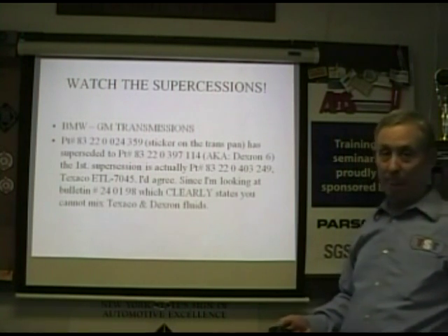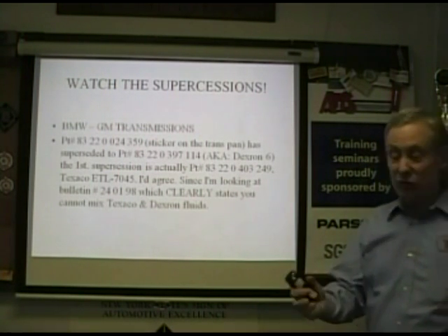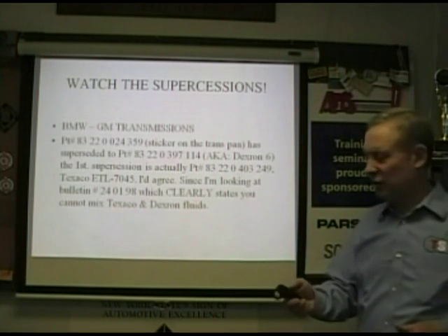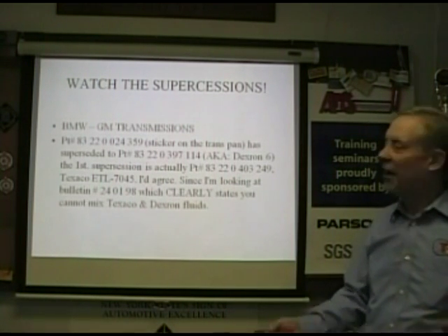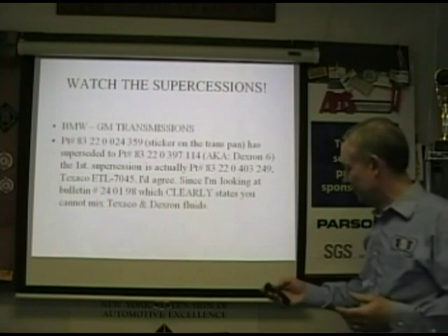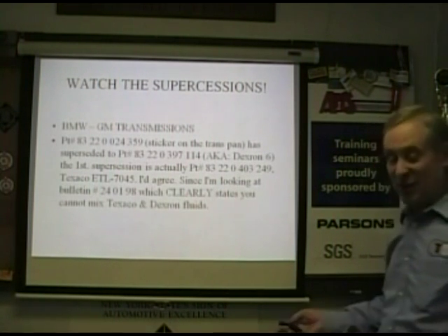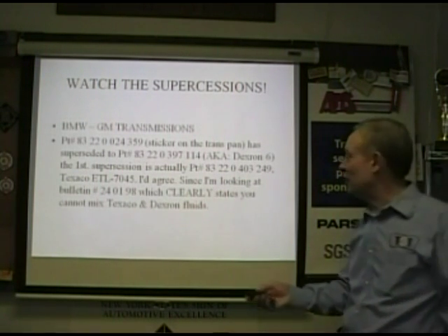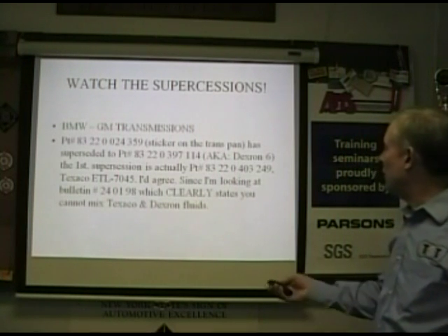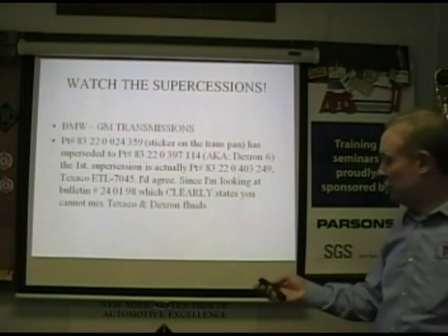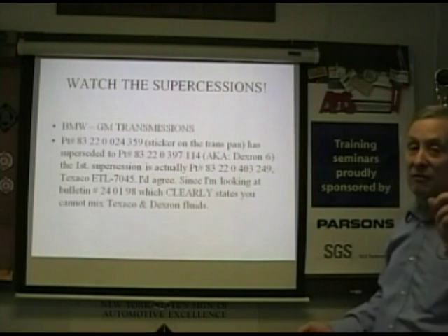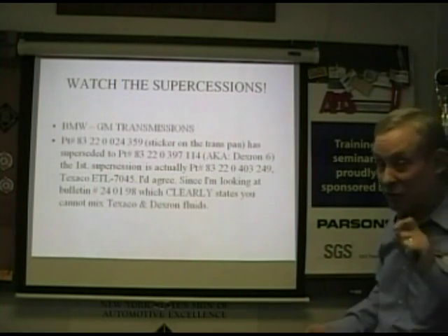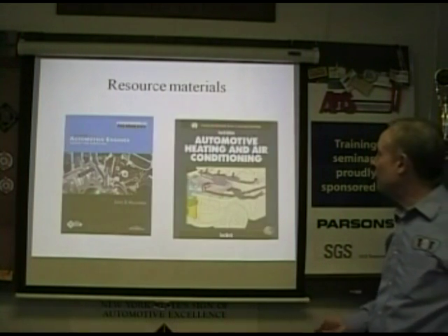Or you do it with a machine like the Flow Dynamics machine, or if you use a Flush It machine, that's really good. Or obviously if you've taken the transmission apart for some reason and it's dry, that makes it easier, just more expensive. But you've already had an issue at that point. Just be aware you can't mix those two fluids that are not compatible with the transmission. They can't be mixed.